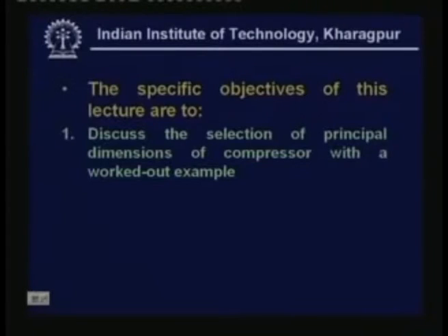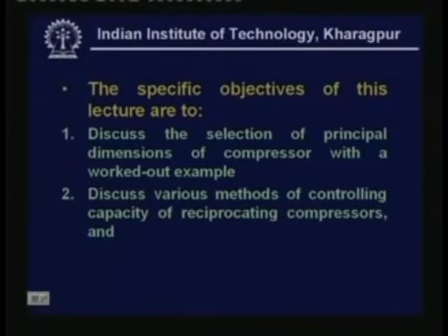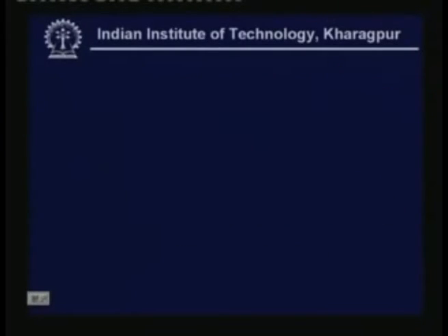So the specific objectives of this particular lesson are to discuss the selection of principal dimensions of compressor with a worked out example, then to discuss various methods of controlling capacity of reciprocating compressors and discuss compressor lubrication.